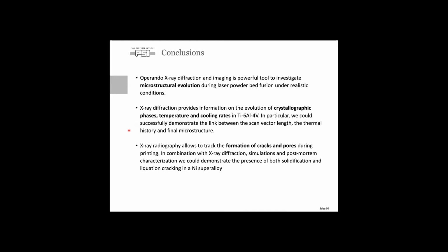So this brings me to the end of the presentation. I hope I've shown you that operando X-ray diffraction and also imaging are powerful tools to investigate microstructure evolution in laser powder bed fusion, in conditions that mimic quite well what is happening in commercial printers. I've shown you by X-ray diffraction how we can follow in Ti-6Al-4V the crystallographic phases, the temperature, and also cooling rates during printing.